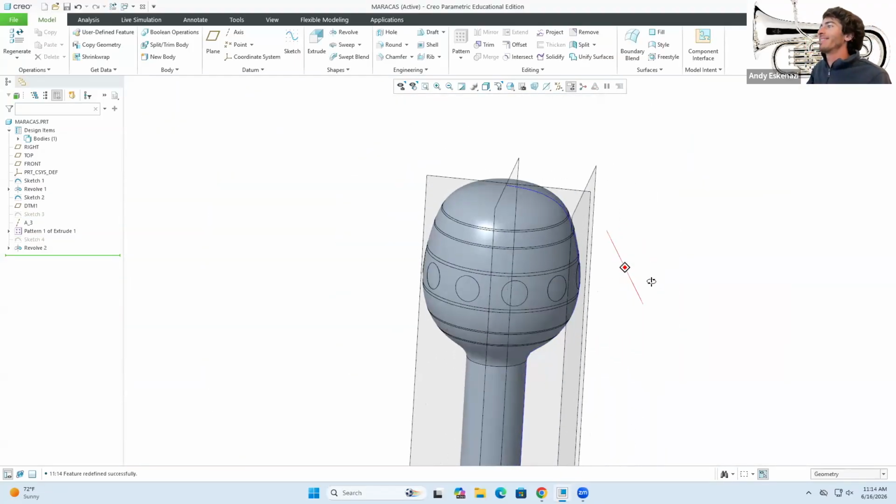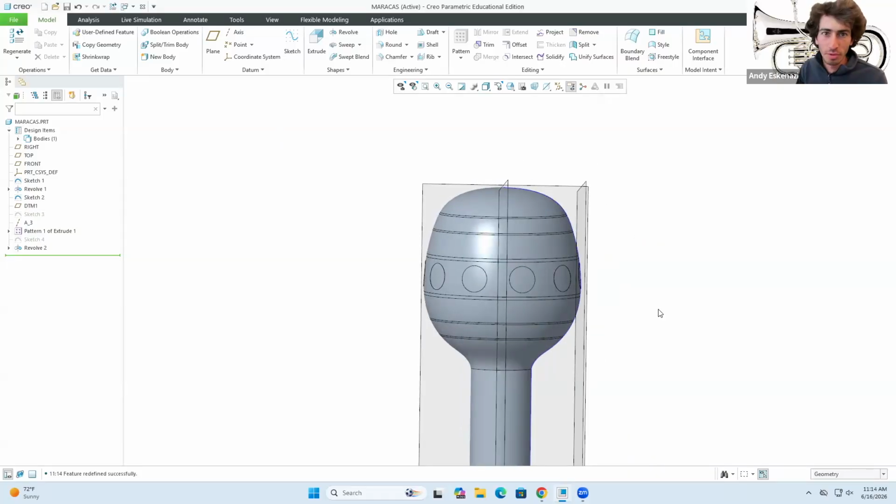So this is a technique, right, in order to more or less achieve the results that you want. It's not perfect. And the problem really with Creo is that sometimes there's commands that they do have something that's called a wrap command, where, for instance, you're able to draw a sketch and it's able to wrap around the surface. But there's a few problems. First, it doesn't work quite cleanly. I've used it in the past already, and it doesn't. I prefer this technique here in Creo.